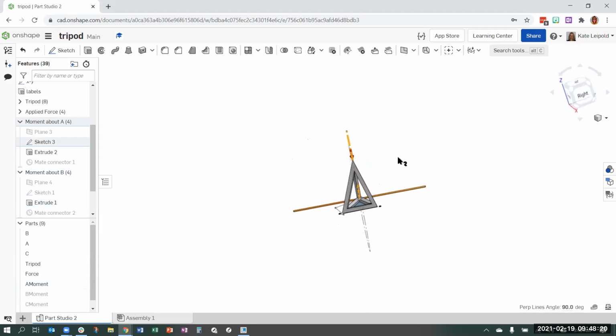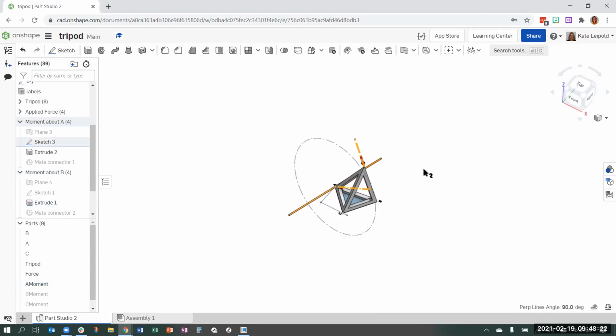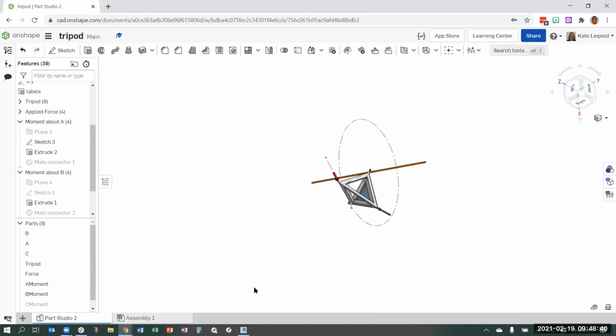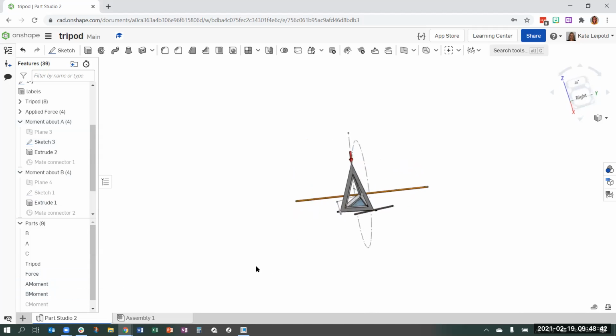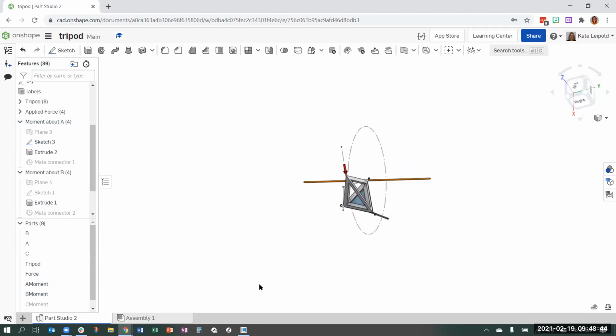The position vector and the force vector live in the same plane. Perpendicular to that plane, I have the axis of revolution, and this has a length relative to the diameter. If I were to show the same length on B, it would be shorter, because it has that smaller tendency to rotate.